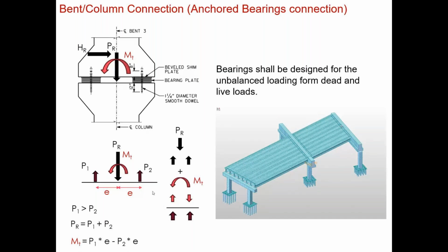But even if you end up with an extreme torsion situation from live load, dead load, or out-of-plane loads that transforms one of those forces into a tension force, then you want to make sure that you have anchors connecting the cap to the column that are designed for this tension load.